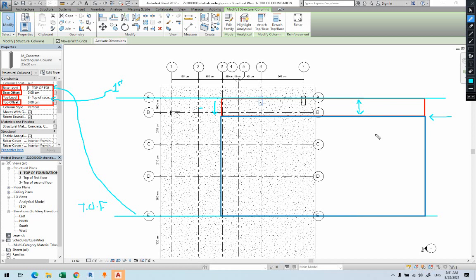So whenever you want to do a wall that goes till the bottom of the beam, you will know the beam. So you can do the beam before, then you can do the wall afterward. Or it doesn't matter because you have the plans, so you can add the wall using offsetting, taking care of the height of the beam. This is what we call offsetting. Now the base offset is basically if you want to start somewhere, not from here. So this is the base offset, whether up or down, you will offset this one up and down.